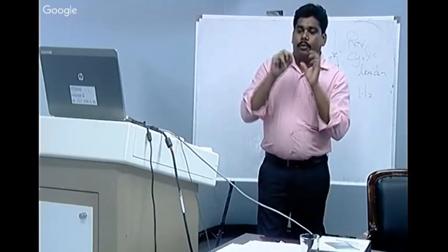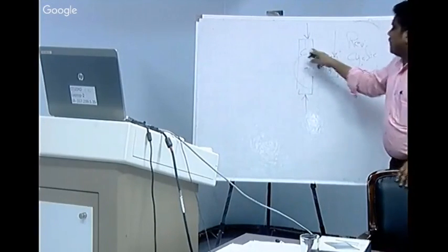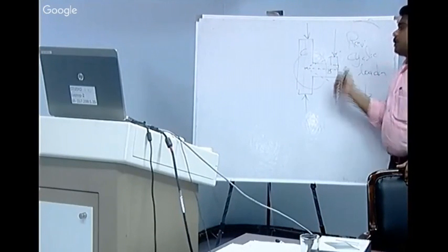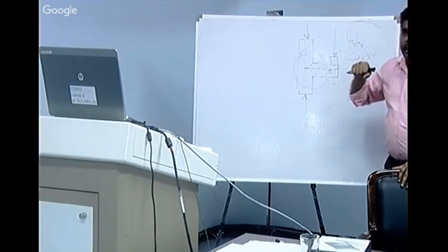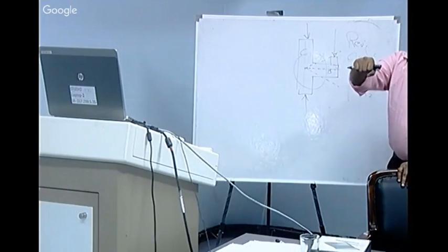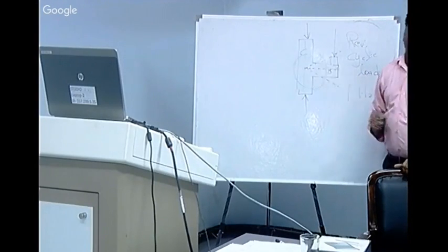If you want to see the performance, you have to use a slow motion camera to understand the behavior of failure. Similarly, if you want to understand the behavior of a joint or a beam or a column, we have to use quasi-static loading, which will apply lateral load at a very small displacement rate. So that will help us understand the cyclic behavior.